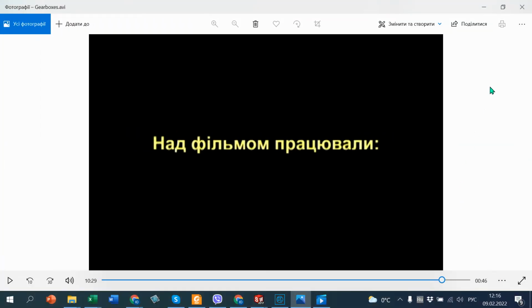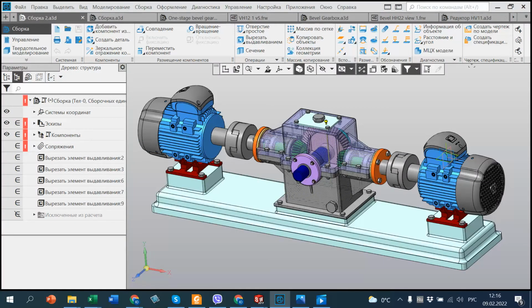Of course, you can't make all of them, and that's why we consider only one type, the bevel transfer. Bevel transfer means that the main element of the gearbox is two cone wheels, and all the variants we make will have different directions of input and output shafts.